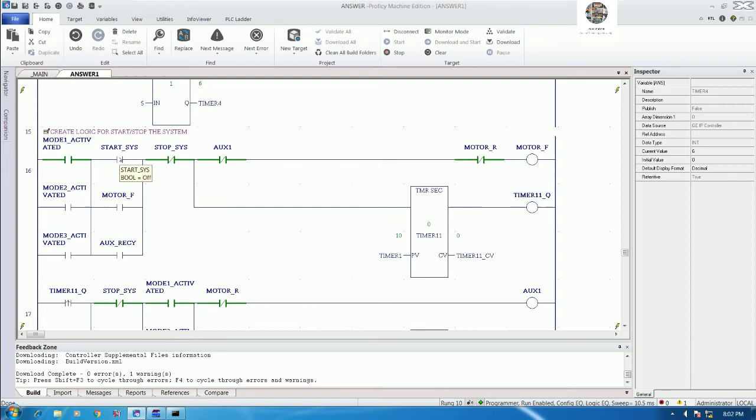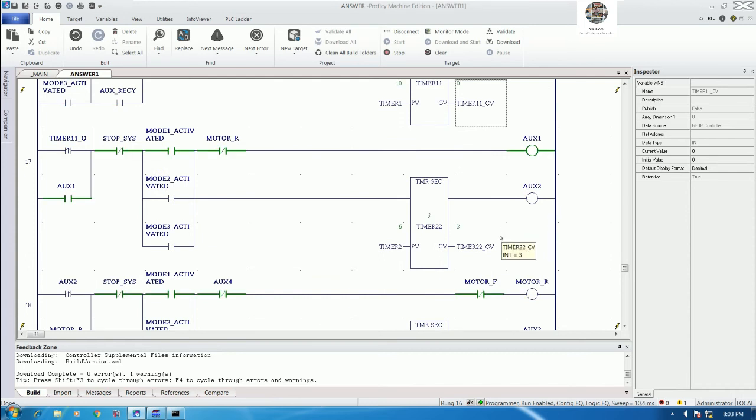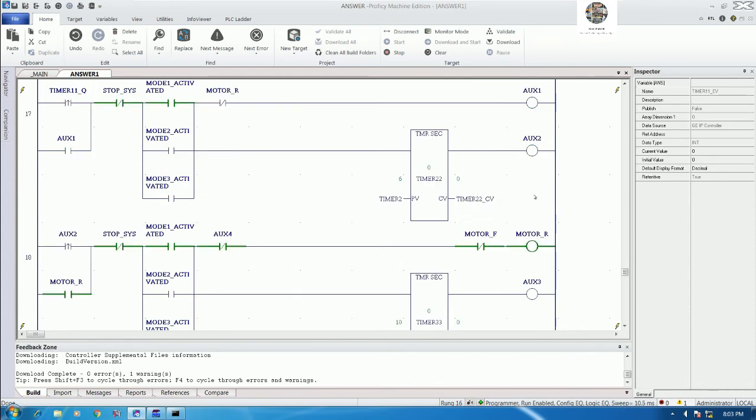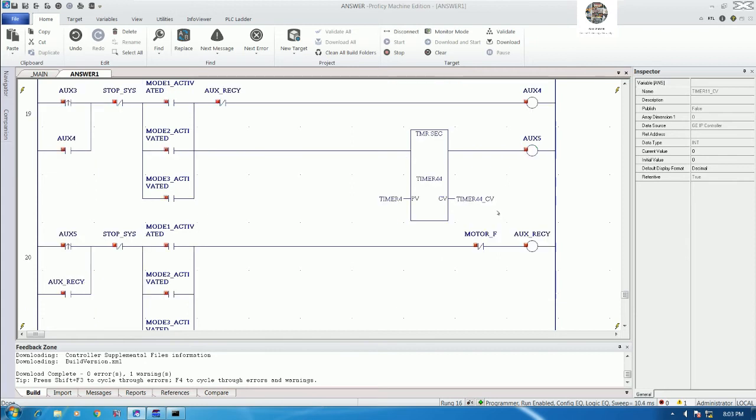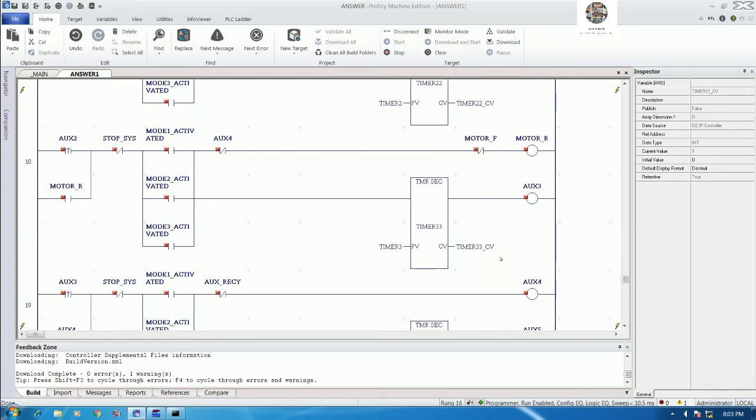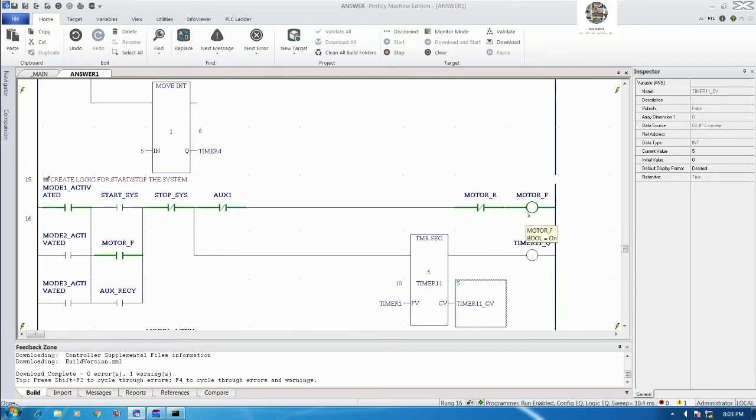And the condition is ready to start here. If I push F12 to start the system, let's see, the system is activated and running the forward signal. After that it stops for 6 seconds, then runs reverse. After 10 seconds it will stop the system again for 6 seconds. It will recycle to start the motor forward again. Here, the motor runs forward again.